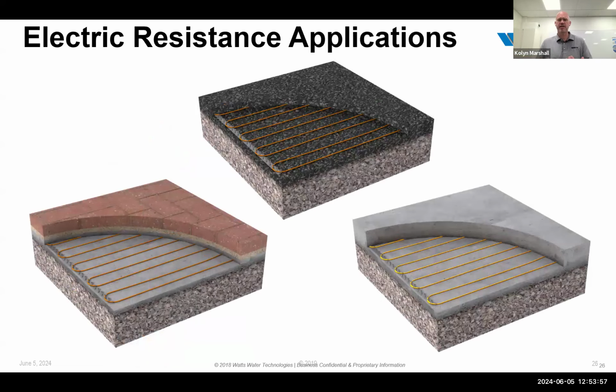Applications that we typically see, concrete slabs are the primary ones that you'll see for snow melting, followed closely behind with brick and sand and brick paver applications. Tubing is going to be embedded in the concrete, as we mentioned. If it's a sand and brick paver, it's going to be embedded in the sand bed below the brick. And you want to make sure that when a sand and brick paver system is installed, they lay down the sand, they put the bricks on top, and they usually vibrate the bricks down into the sand bed. And that draws up the sand between the bricks and locks them in place.